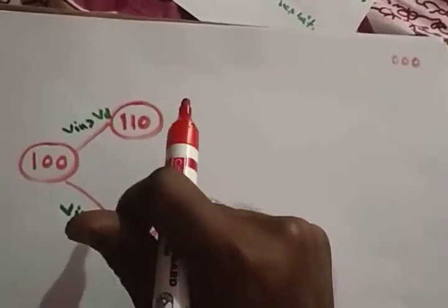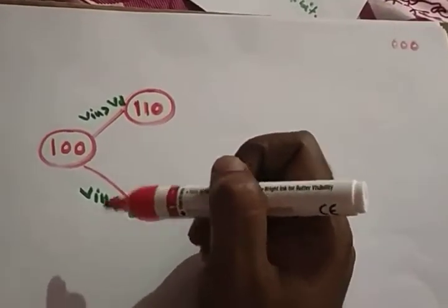If you take the 3 bits, the starting value is 0, 0, 0. What is the function of the successive approximation register? It will set the MSB at the start. That's why 1, 0, 0. After that, there will be 2 possibilities, right? Vin greater than VD, or Vin less than VD. The function is the same as the counter type.